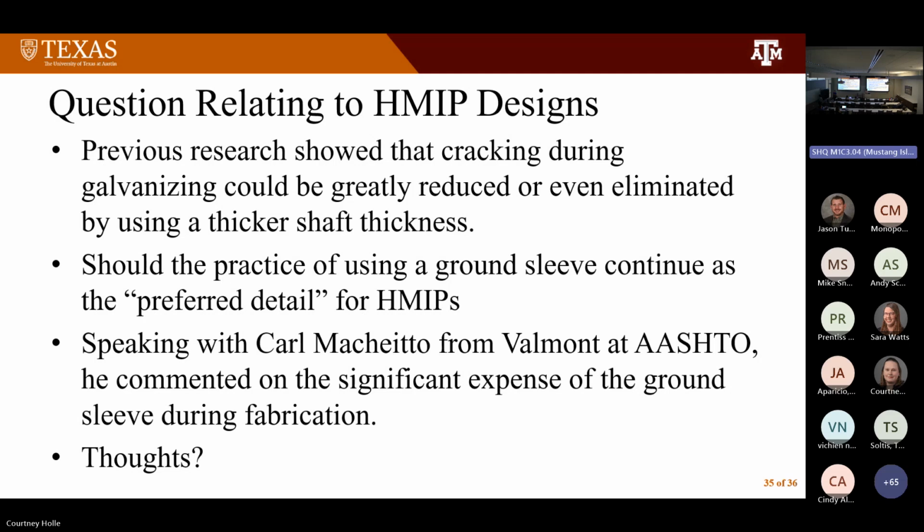Yeah, but again, I'll focus on high mast poles, which I've done a lot of in the past. You say, well, this has been out there for 30 years and it's got cracks in it. Well, we found that a lot of these things happened when they pulled it out of the galvanizing. It's already cracked. The worry is, is that crack growing? And that's where you can say, you've got some small cracking, you need to come back in a year or 2 years and look at this again and recharacterize it. Has the cracking changed? If it hasn't, then move on to the next pole. It's not a big issue.